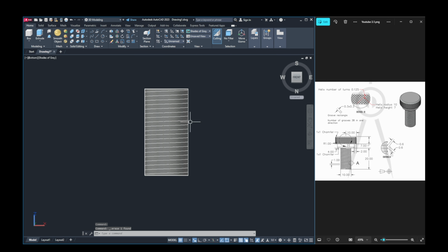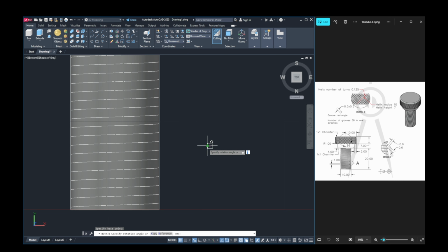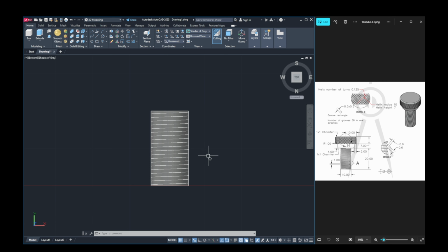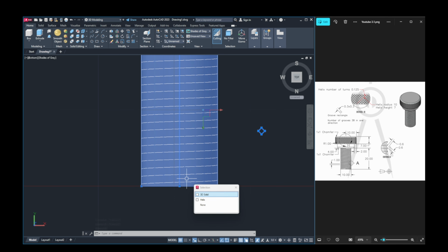Let's change it. First of all, change this to axis XY and REC for rectangle 0.6, tab 0.6. Now rotate this to 45 degree. Okay. Now place this rectangle on this endpoint, but we will not be able to find out the endpoints.